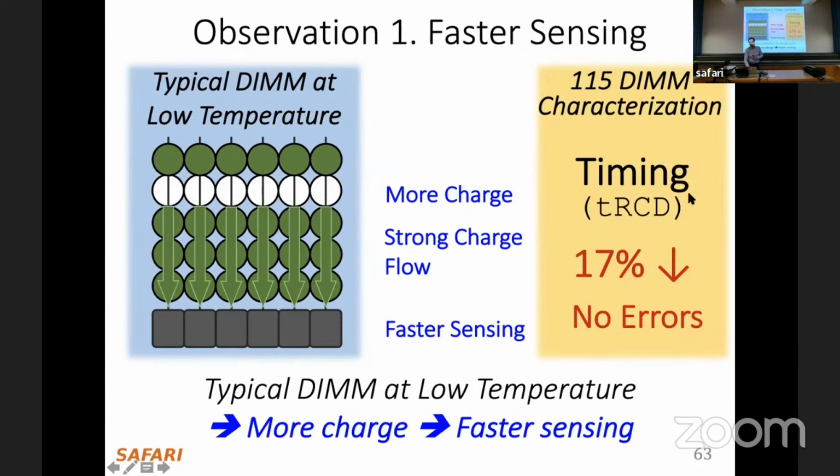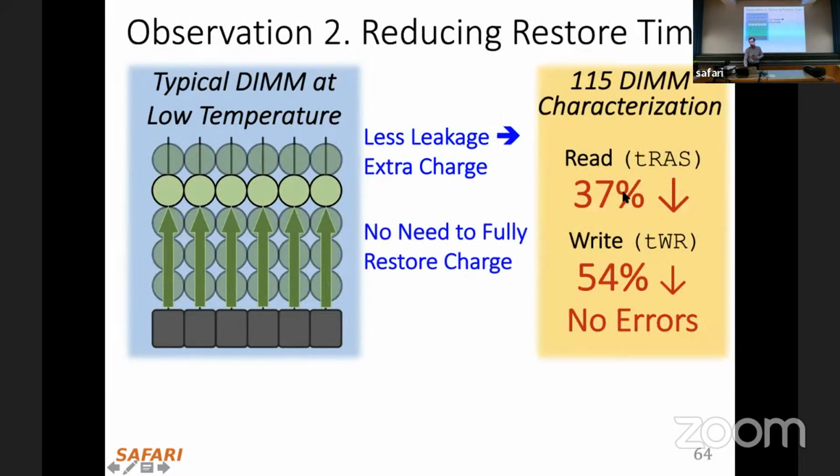Like this is the activation latency of a row, and this is the restoration latency after you do a read or a write. We're not going to change the frequency, but you can also do that separately. And this latency decides the DRAM frequency or something? Latency, essentially. Like how long you need to wait before you are sure that the data is in the row buffer, for example.